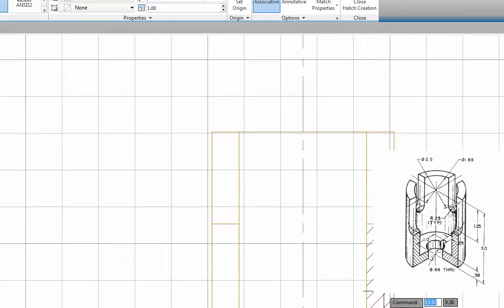As long as your object does not have that same angle, in this case 45 degrees, which is what ANSI 31 is at, you can use ANSI 31 as your sectioning line. If it does have a 45-degree angle on it, you'll want to change and use a different angle of rotation. And typically it's 30, 60, 90, 45 are the basic settings. You could then move to 22.5 and 15 degrees if necessary. And again, you want to make sure that you do not align the section lines with an angled surface.